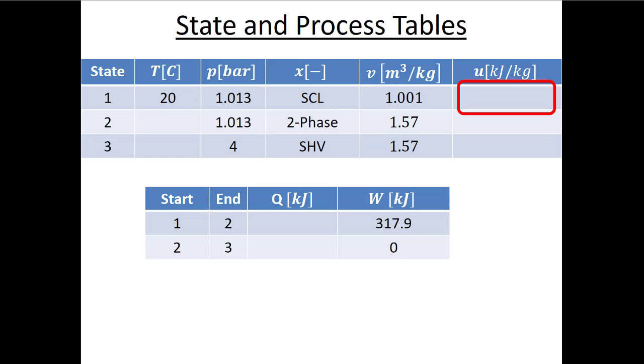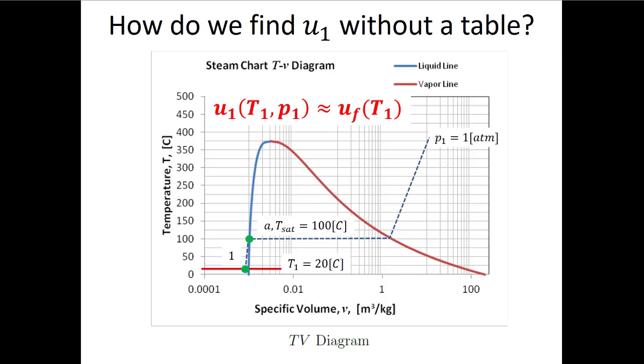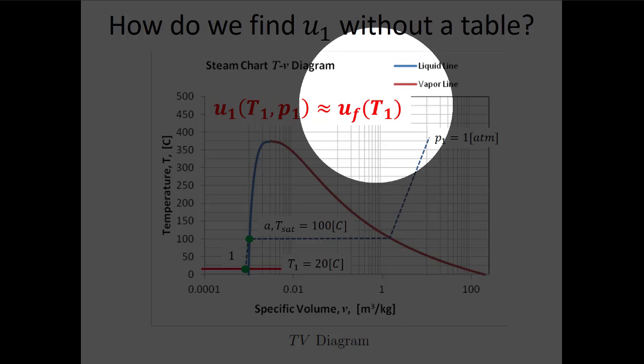This first one, subcooled liquid, it's funny because maybe a week or two ago I would say, man, I hate working with subcooled liquids because usually it means I have to do this double interpolation thing, which is a huge pain. But now I love subcooled liquids because I have this incompressibility assumption, right? So I'm going to assume that all these properties are the same as if we had the saturated liquid at the same temperature.